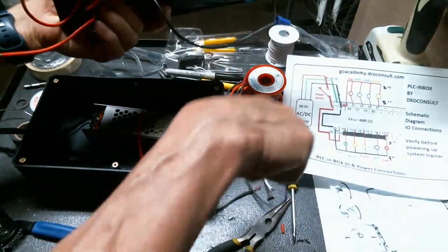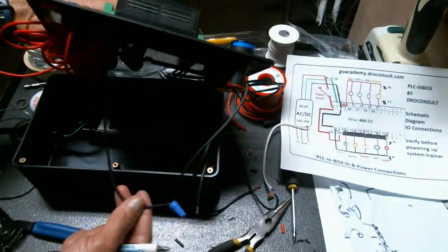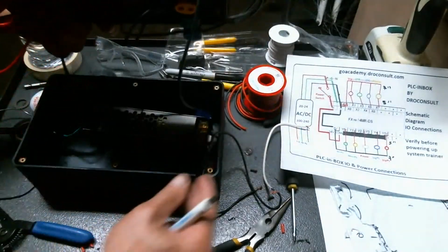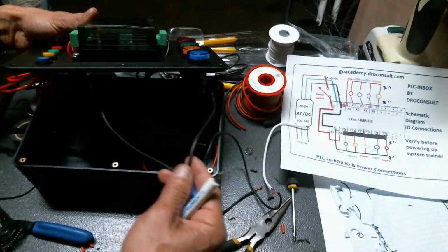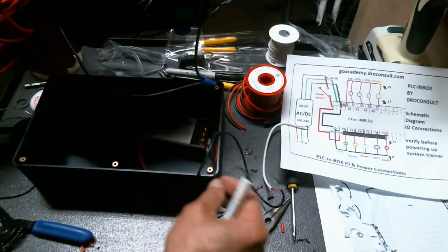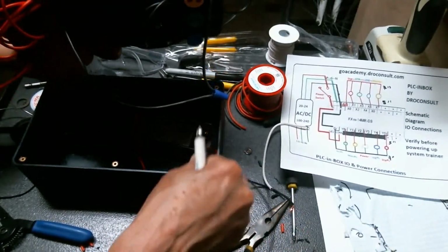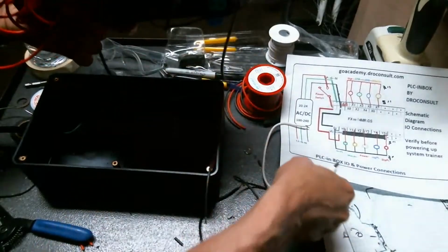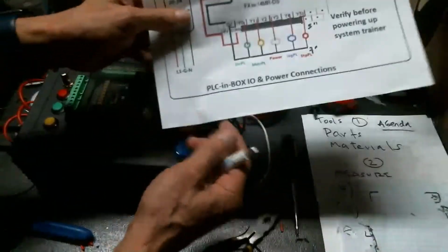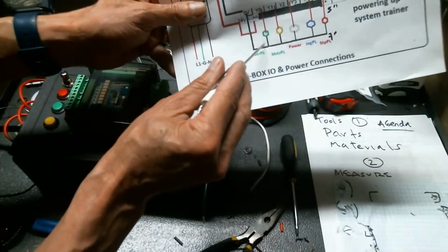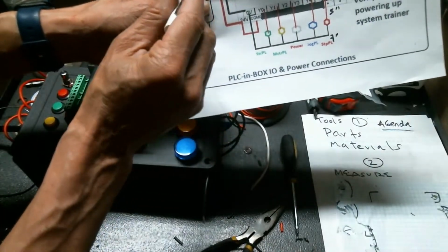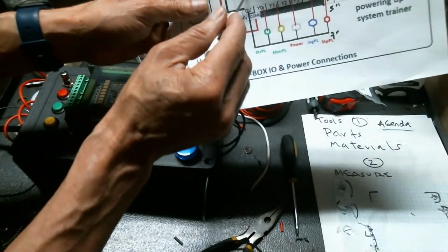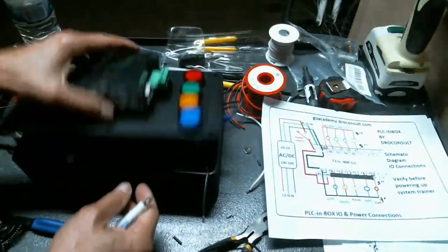If we look at our box, it needs both negative and positive, right? So I'm going to make it easy on us. I'm going to join the incoming negative wire to this loop. So this is where we are. I already got this loop from this point to this point, right? I'm going to join this incoming negative to this loop, right? How am I going to do that?